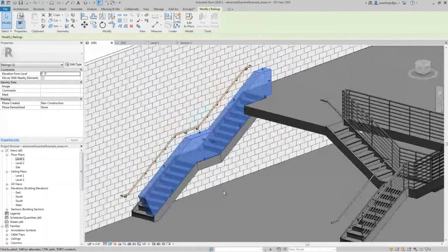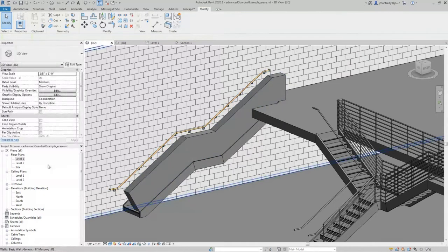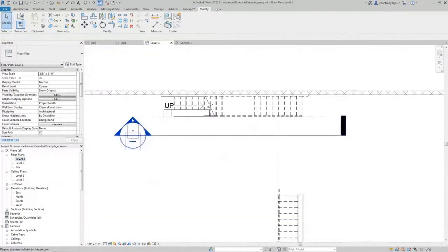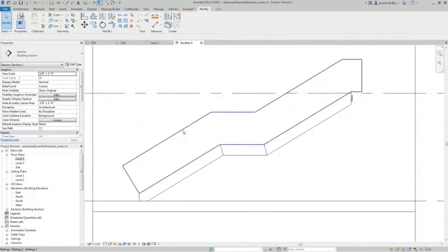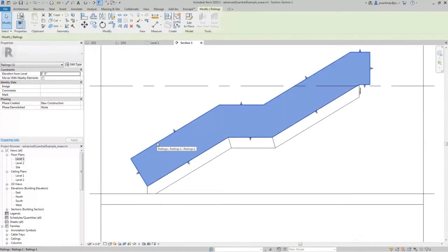And what I'll do is I'll use this wall to trace my railing as a guide. And then I'll add the vertical members and other pieces and parts of this model as I go. So let's go back to elevation. I drew this sort of section here. So I take this and I go back. I click on the wall and I edit and place that model.